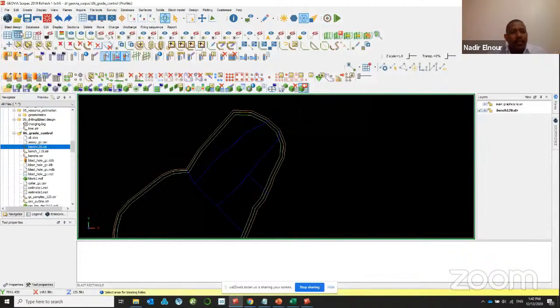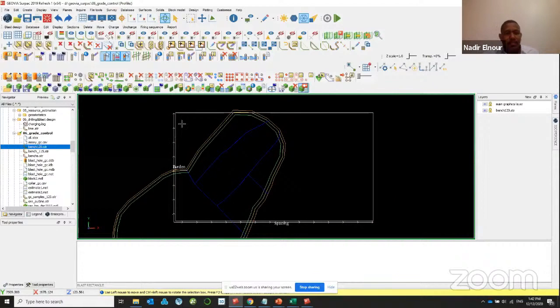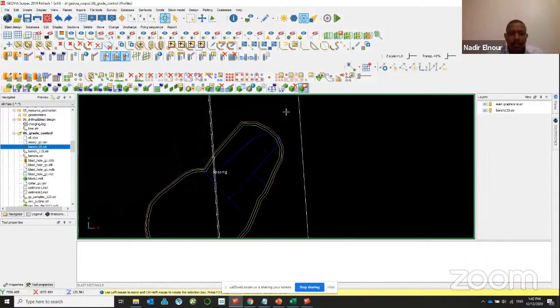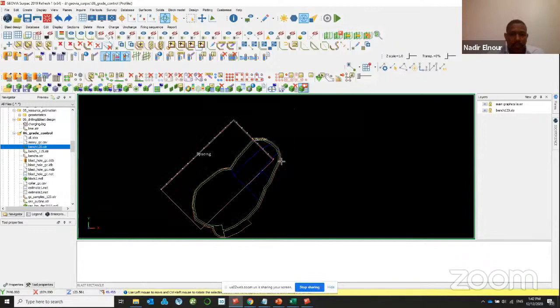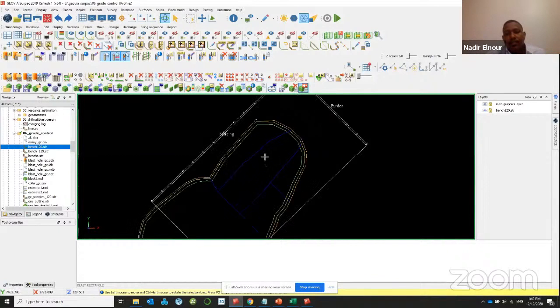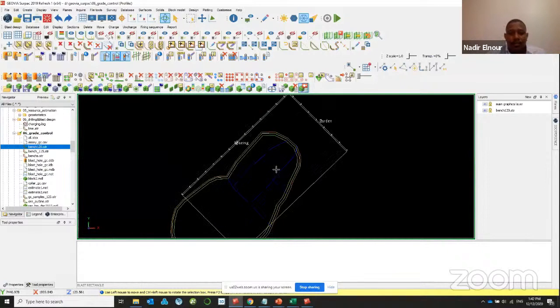Just try this. You can just generate a pattern design. You can just drag and drop, and then you need to define your bearing and spacing. You just need to press Control and rotate. After that, you release everything and move until you locate that segment inside your areas. Now you don't worry that the box is bigger than the area here, because we constrain the polygon.